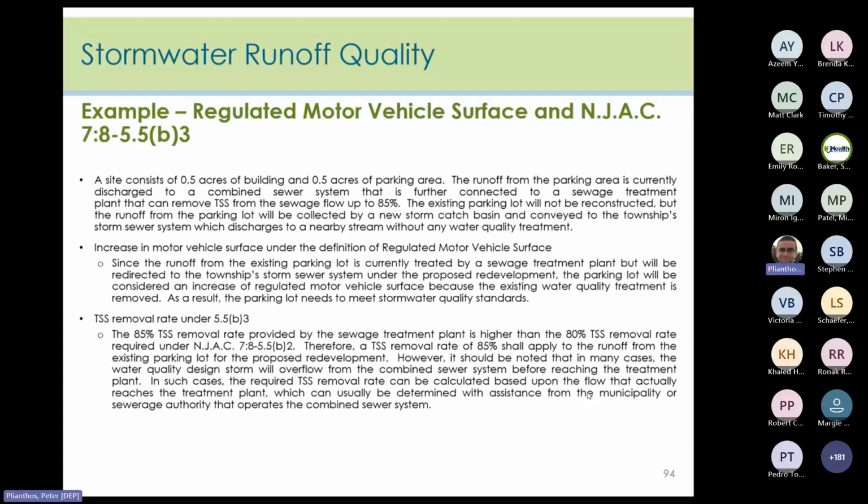The runoff from the parking area is currently discharged to a combined sewer system that is further connected to a sewage treatment plant that can remove TSS from the sewage flow up to 85%. The existing parking lot will not be reconstructed, but the runoff from the parking lot will be collected by a new storm catch basin and conveyed to the township's storm sewer system, which discharges to a nearby stream without any water quality treatment.